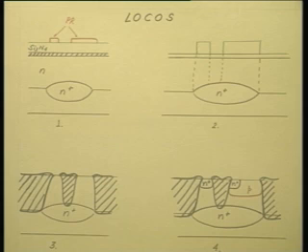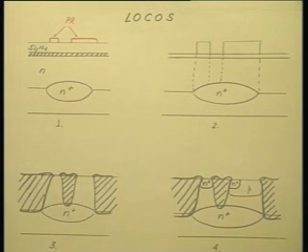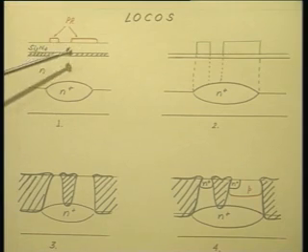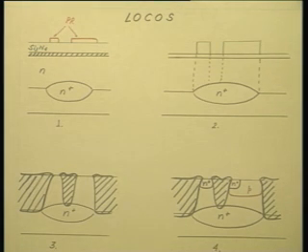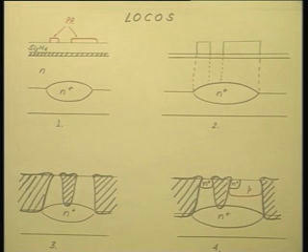For bipolar junction transistor, however, essentially this LOCOS technique is used for isolation, that is, protect the active region using silicon nitride, etch by a calculated amount so that the resulting oxide comes only up to the top surface, carry out the oxidation in order to realize the isolation regions, and then have your base, emitter and collector contact diffusion.